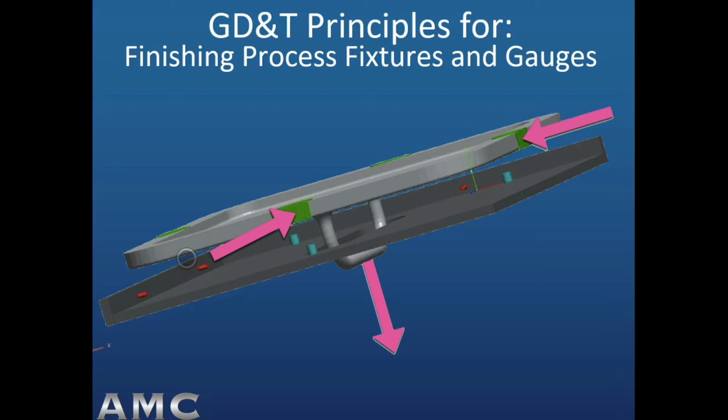So here's how these functional gauges and fixtures work. The blue pins are the datum A targets for checking the flatness of the casting with respect to its overall finished assembly and machining surfaces. If the casting is not flat or twisted in some way and not sitting reliably flat on these three primary datum targets, then the casting will not be machined uniformly across its entire profile. There'll be thick and thin areas in the walls across the entire rectangular profile, which would ultimately result in rejection.